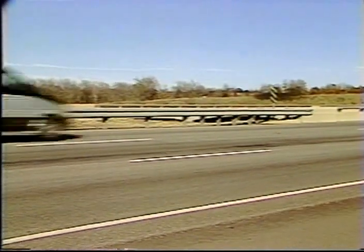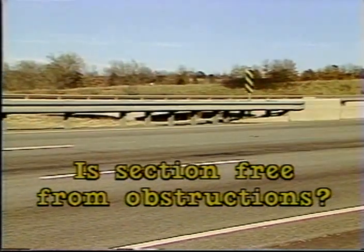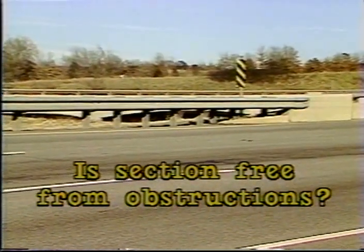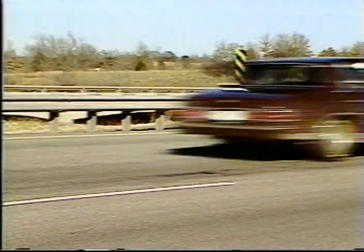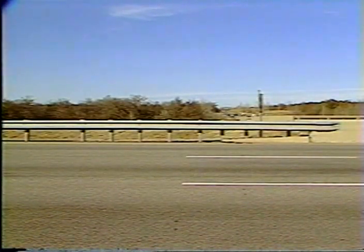Like the other barrier sections, see that the transition section is free from curbs, abutment ends, or other obstacles that might vault, snag, or tumble a vehicle. The height of the transition section barrier is very important. It must be correctly positioned at each end to match the height of the barrier it will connect to.